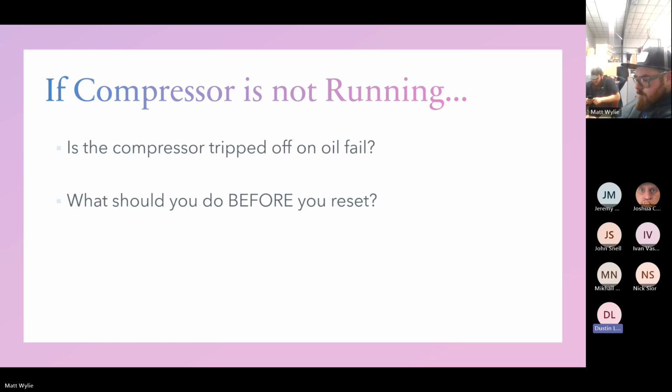You know, Walmart Twin Falls, for example, it's not a rack system, it's still just a single system. So it's not only at grocery stores, but those have oil fails on them, and it's the same concept. Too low of superheat can cause oil fails.